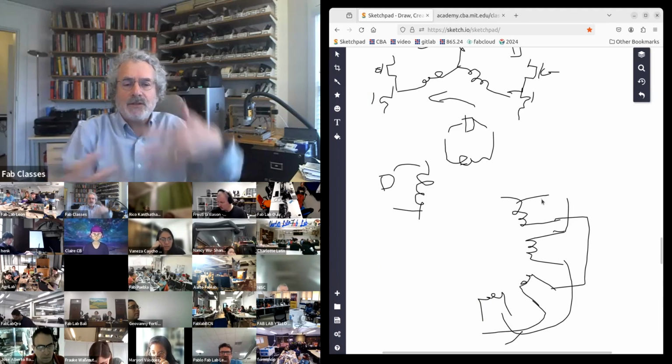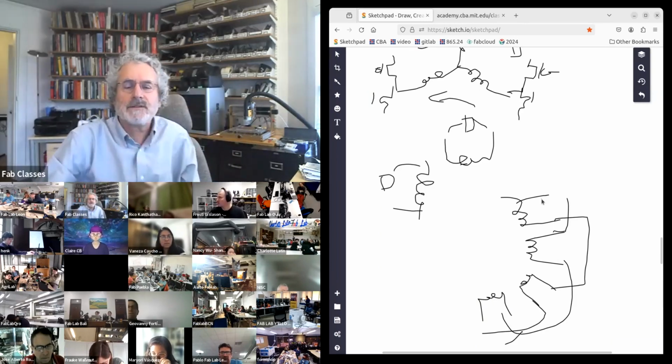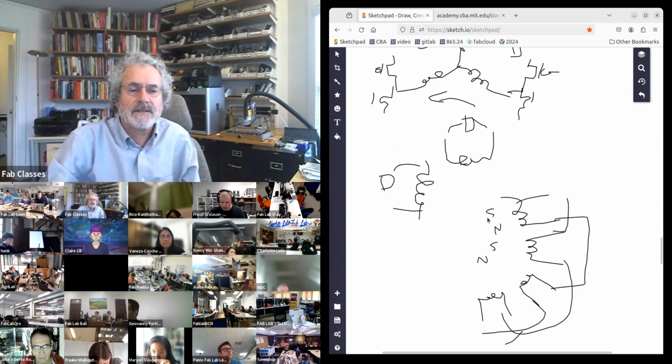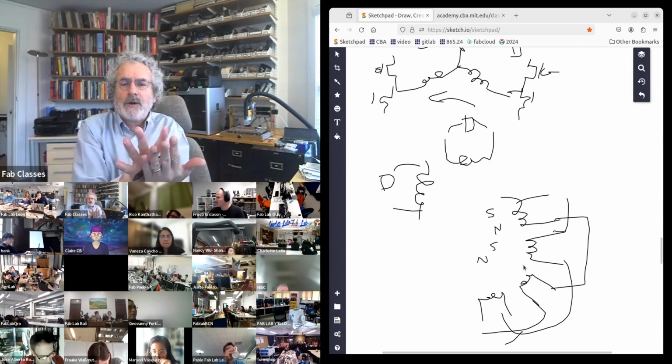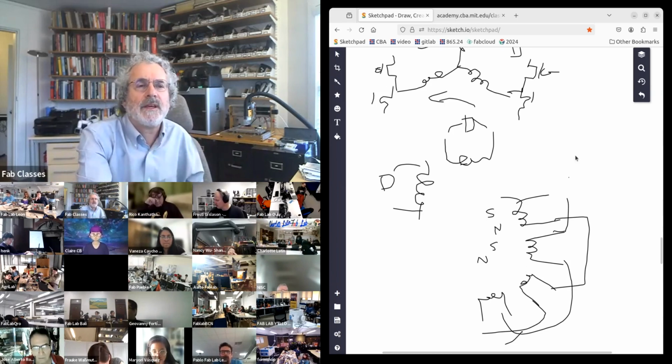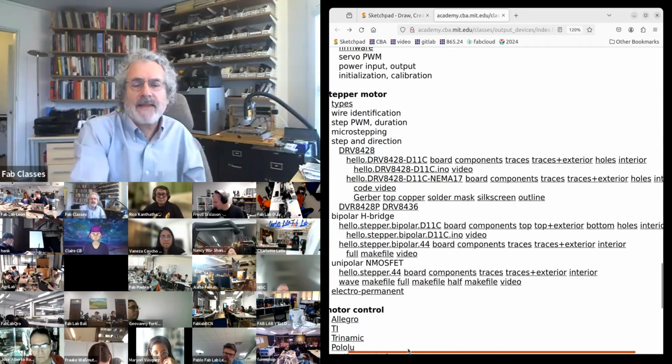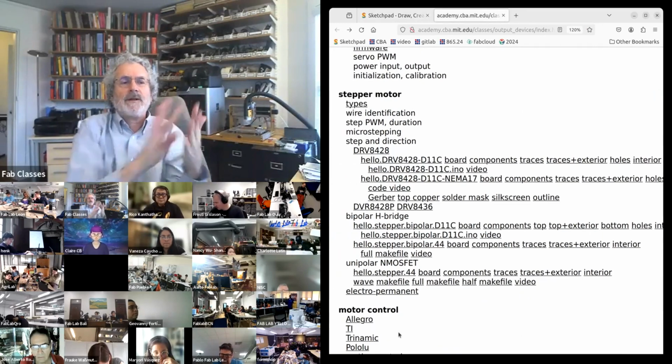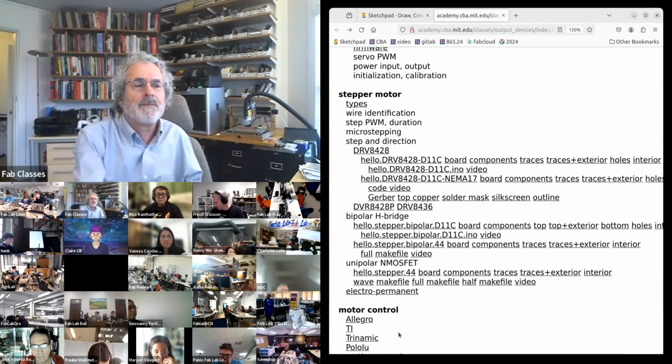It's two sets of interleaved coils, and then here we have north-south, north-south magnets. Depending on which coil is energized, there's one orientation where it's happy. Then when you energize the next set of coils, it's unhappy and has to rotate to realign. So the stepper is specified by that step angle to align the coil, and 1.8 degrees is typical.